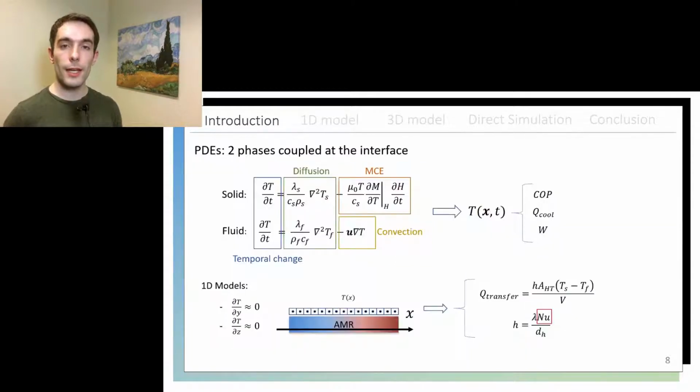Another way of investigating the dynamics of magnetic regenerators would be through numerical modeling. These are much less expensive to build than prototypes. However, their solution relies on the hypotheses and models we choose for them, so we have to check that the solution is really physical. At minimum, we have to solve the energy equations for the solid and for the fluid domain too, because it's the substance that links all the thermodynamic cycles and the heat exchangers together. And if we apply the conservation of energy to these two domains, we get the following partial differential equations.